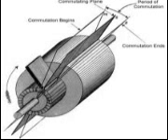external circuit. A flexible, braided copper conductor, called a pigtail, connects each brush to the external circuit. The brushes, usually made of high-grade carbon and held in place by brush holders insulated from the frame, are free to slide up and down in their holders in order to follow any irregularities in the surface of the commutator.